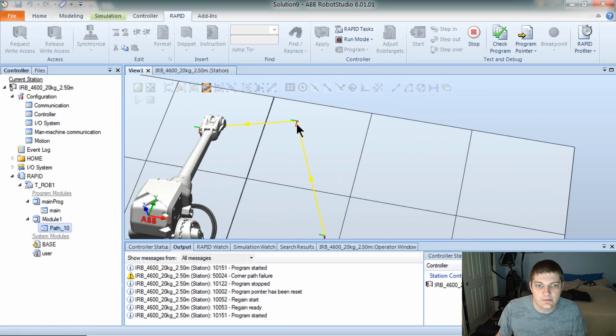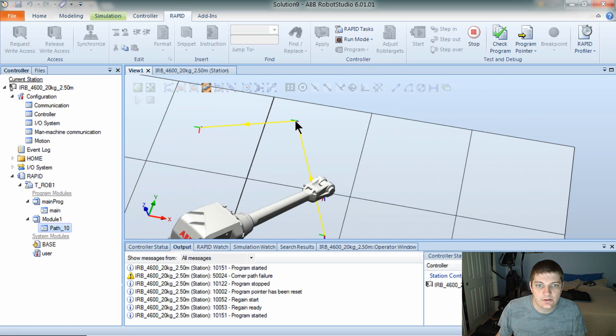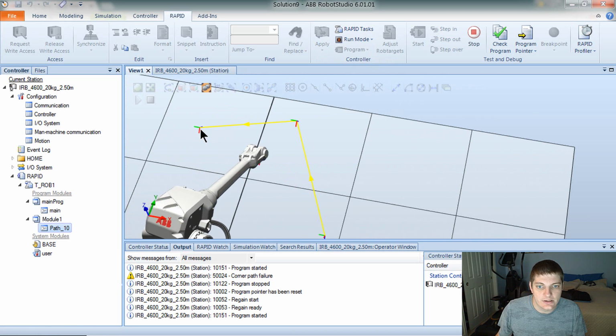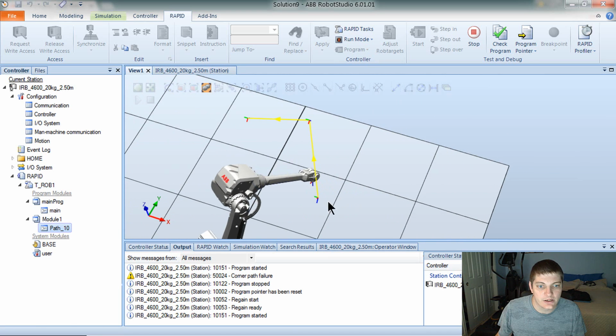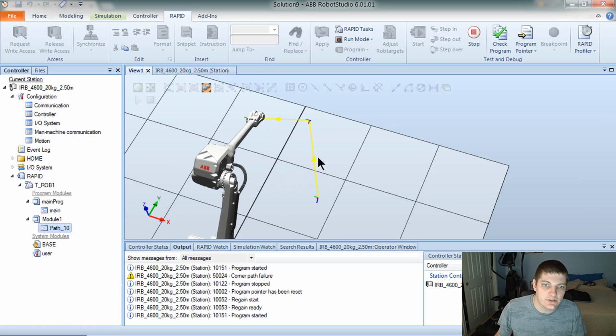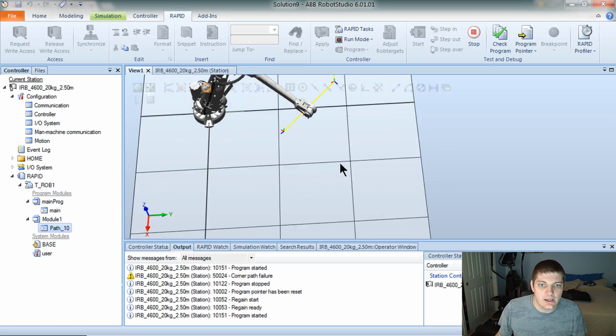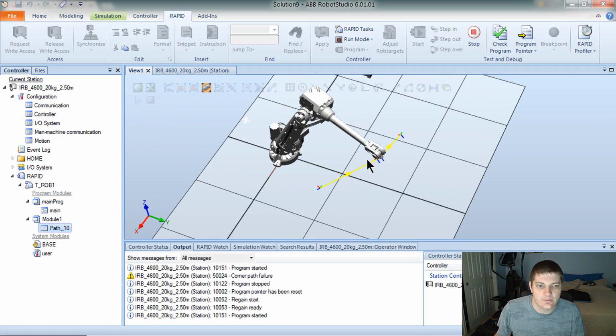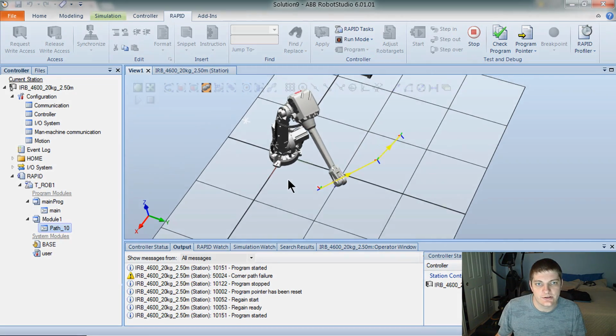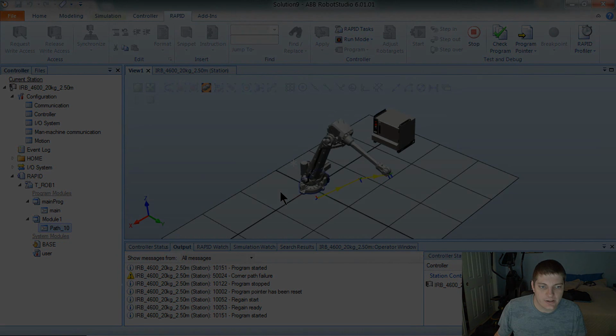He's hitting this point. He's coming within a zone of this point, which we talked about earlier, and then he's coming near actually to a zone around this point as well because we're coming back. So he's zoning each one of these points all the way around, and that'll get you the most speed out of the robot. And it also has some other tricks about getting across configurations and things like that, but that's out of the scope of this episode. So that's about it. This one went a little long, but I got a lot of stuff out of the way that I wanted to explain.